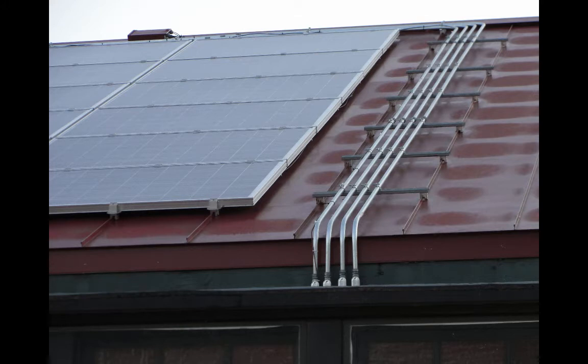Here is an example of multiple conduits instead of one big conduit. So if he just had a couple of wires, like 3 conductors in each conduit, he did not have to do as much derating than if he took a bigger conduit and jammed a whole bunch of conductors in a single conduit. Then he would have had to do different derating. Then he would have had to use more copper and derated the wire differently. So he used smaller conduits, easier to work with for his size of a business. However, some people will do it the other way too.